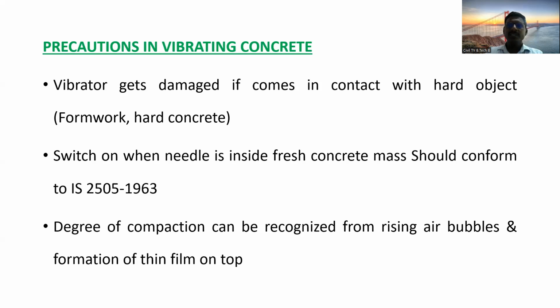Because if air is present in the concrete, voids will be there, the homogeneity of the concrete is lost, and the strength will automatically decrease. Nowadays we generally use vibratory compaction. Why? Because the air voids get removed and the strength increases.